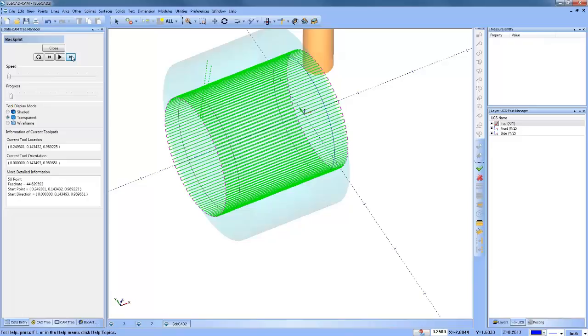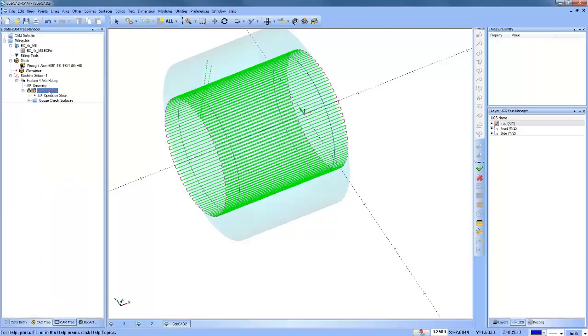These are things that generally you would have to do with the G code directly. You can make those edits in the G code, but depending on the complexity of the part and how many operations, it can be a lot easier to set this stuff right in the toolpath. Again, you had a question about the advanced rough. The toolpath editor you're going to have access to with any of the 3D toolpaths, any of the 2-axis toolpaths, the drilling, 3-axis, 4-axis, all the way up to 5-axis. Does that make sense, Ken?